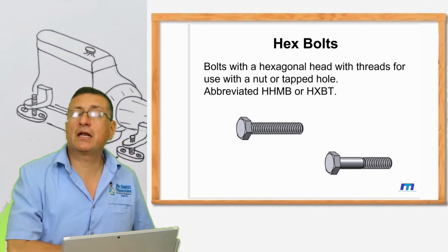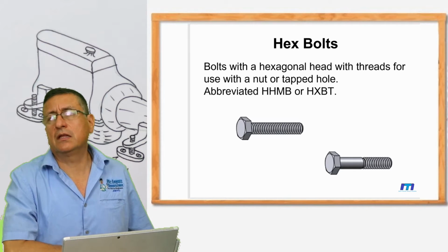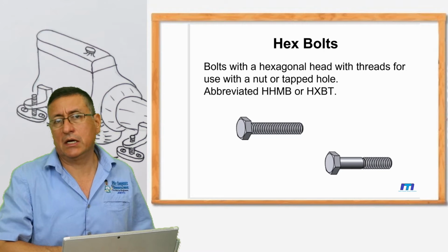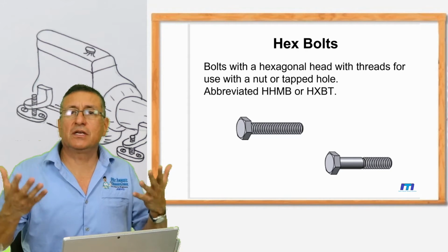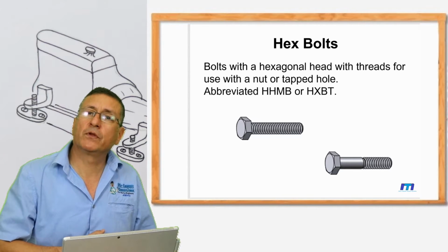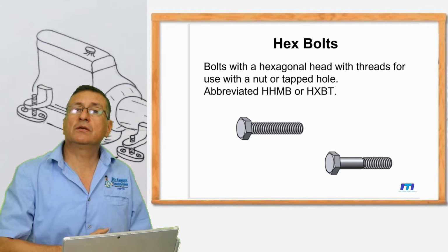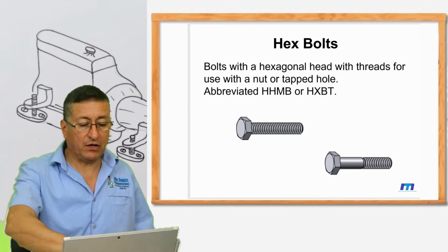Internally in the engine, there are a lot of bolts, not necessarily marine grade, because internally in the engine the environment is surrounded with oil, and the bolts are submerged in the oil, and they don't need to be marine grade. All right, marine grade is when the screw is exposed to the environment, to the salt, to the marine environment.